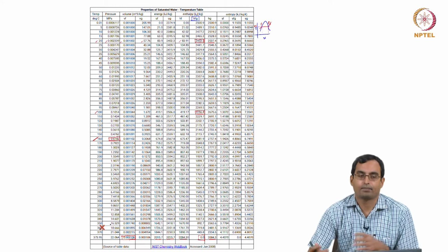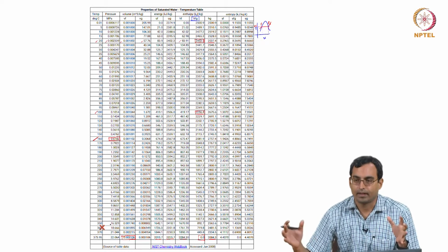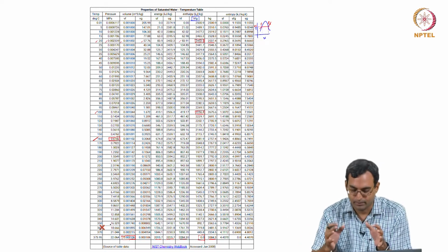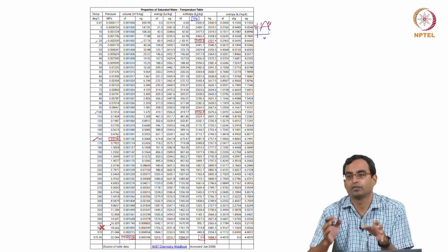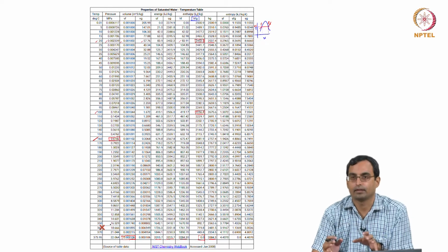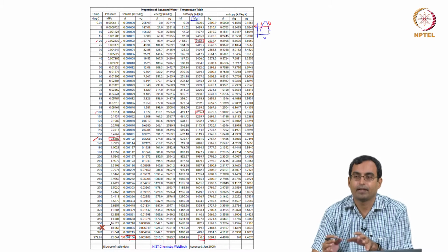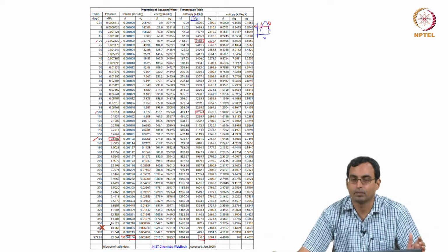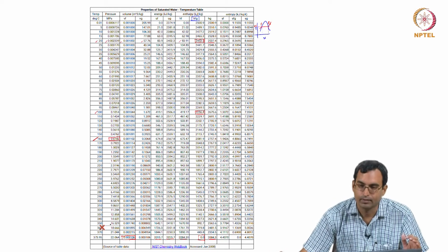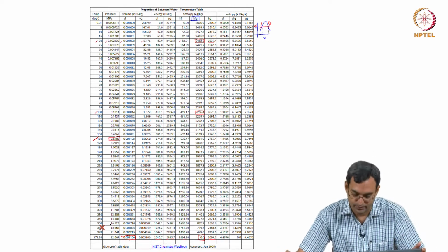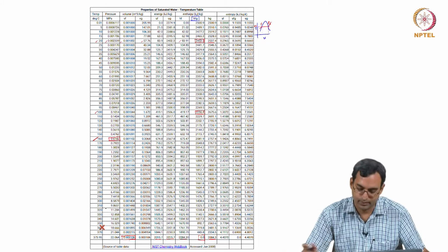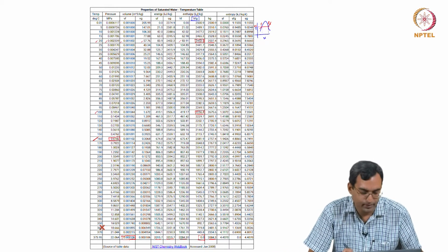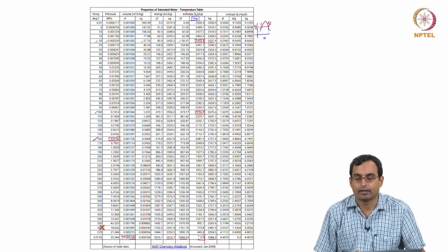So, I have steam at this temperature. If I compressed it and kept it at 16 megapascal, it would be in the two-phase dome. It can come between liquid and vapor, but I am letting it expand so much, which means it is expanded much more than it would be at that condition, which means that it is in the superheated state. So, what I need now is to look at this condition, 350 degrees and 3.5 megapascal, in the superheated tables.